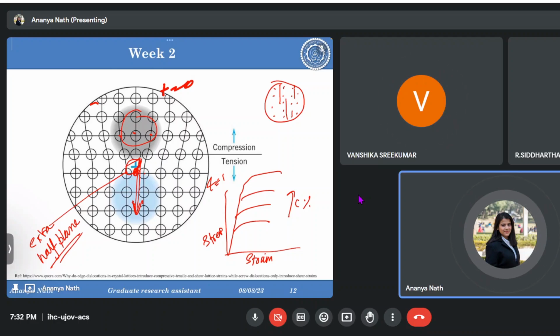Oh, it's the same concept: we are first increasing the strain, increasing the stress, and after one point, if we have gone beyond the yield point, it will start the recovery, means it will try to arrange themselves in such a way that they can lower down the stress inside them, with dislocation movement and then solute atoms following them.